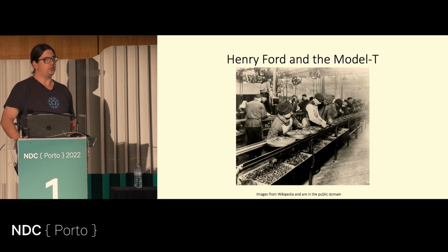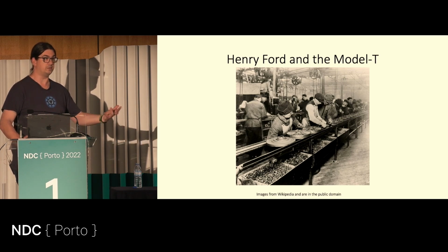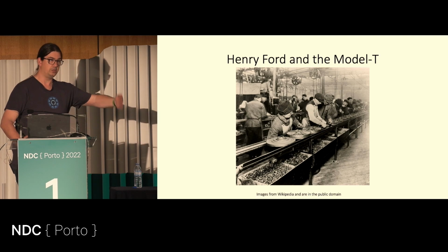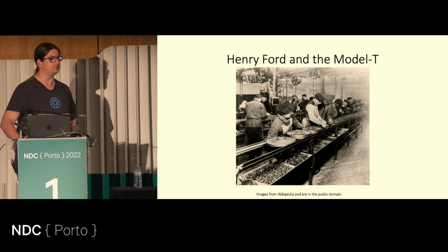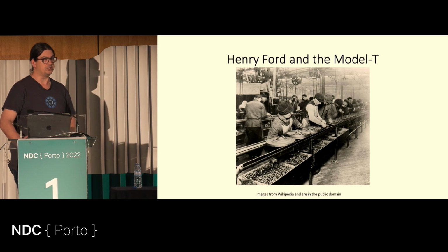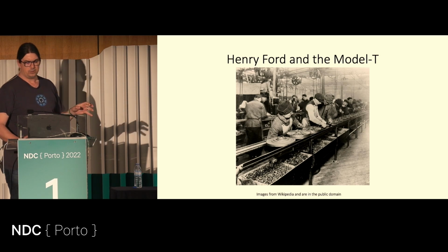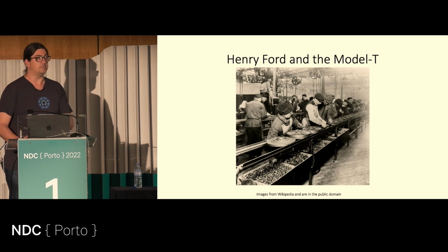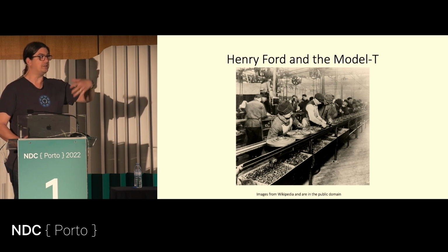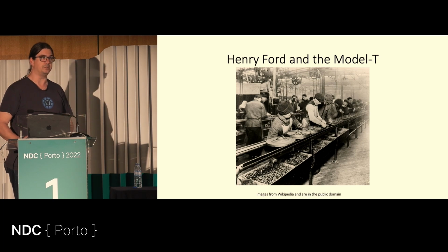But their process was what is known as a push process. They're not manufacturing based on customer demand. The company has set a limit of cars that they want to produce, and then they go through this production line to build that number of cars. So if the boss at the top says, I want 10,000 cars, that's the target they respond to. On the contrary, you have what's called a pull system, where you're not working to a limit set by the company, you're working to customer demand. So you have orders come in, you manufacture a car, send it out to that customer. A bit like what Tesla does, in effect.